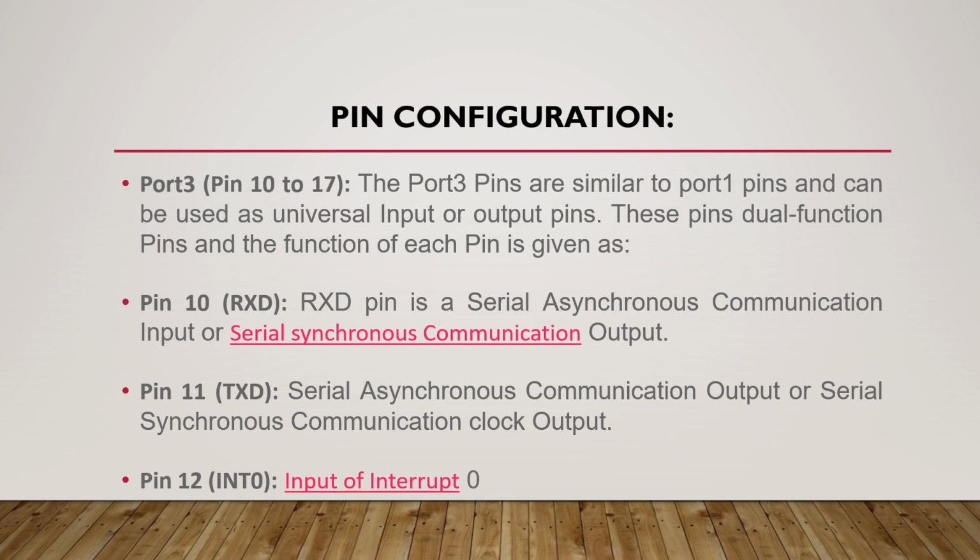Okay, next, the 11th pin. The 11th pin is TxD, the transmitter pin. Whatever data the transmitter transmits is collected with the 11th pin. It is the serial asynchronous communication output or the serial synchronous communication clock output. Here I said synchronous means it follows a clock signal.